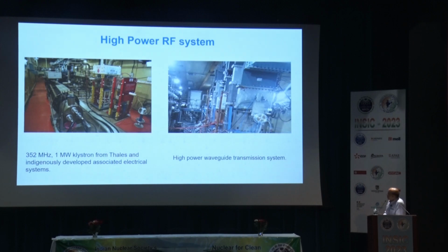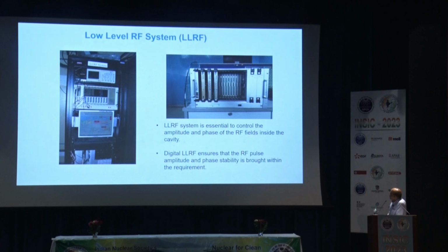So we have a high power RF system here. Except klystrons, we have developed everything, designed everything in BARC and developed several local vendors. Low-level RF system again was designed and developed within BARC and with the local vendors. This is using basically digital technology to bring the amplitude and phase of the accelerating fields to within 1% of amplitude and phase.